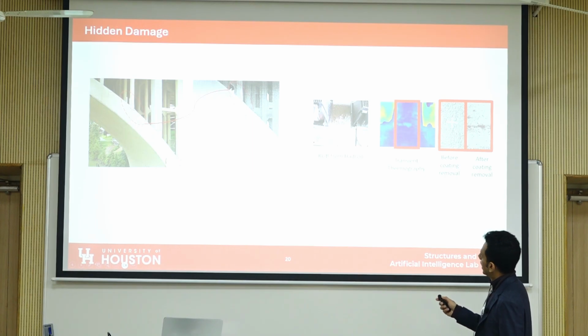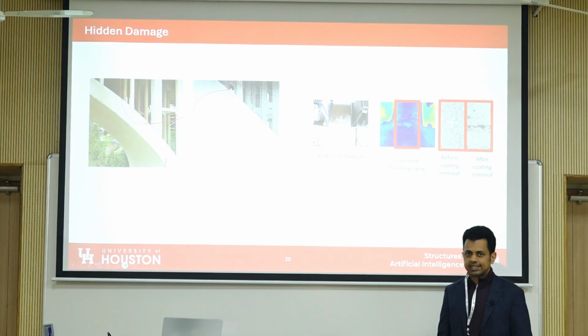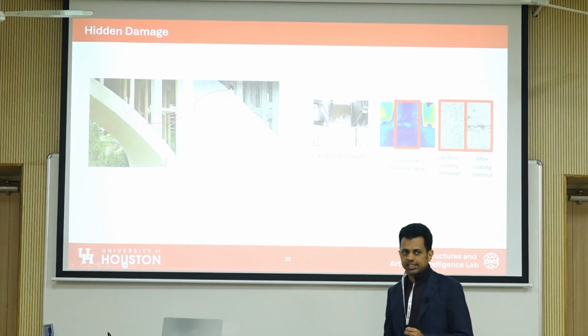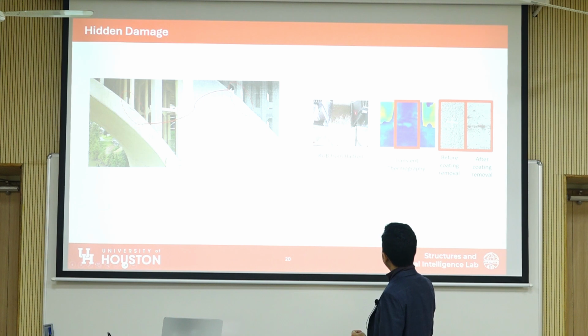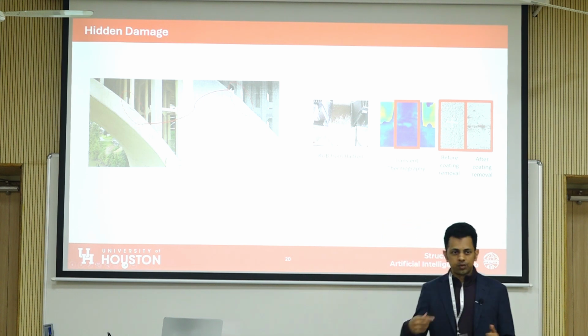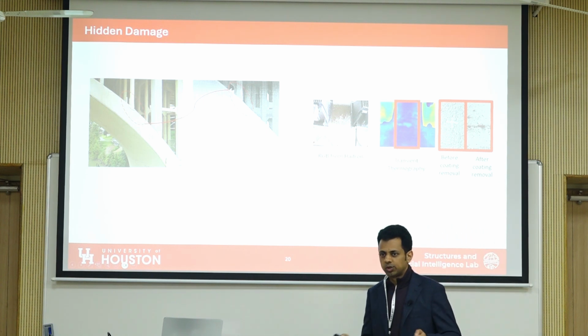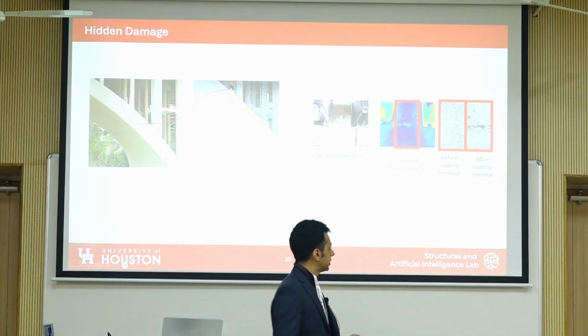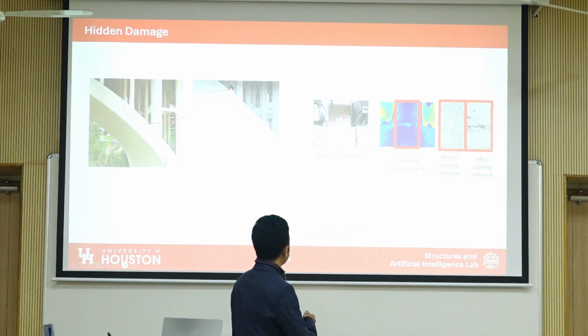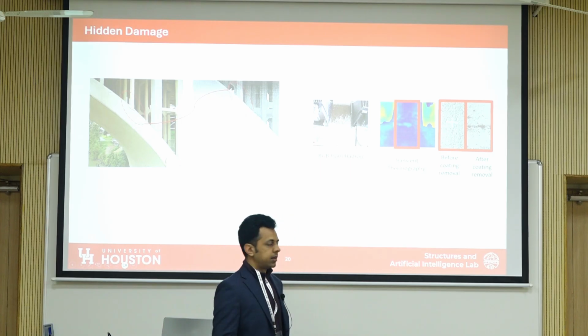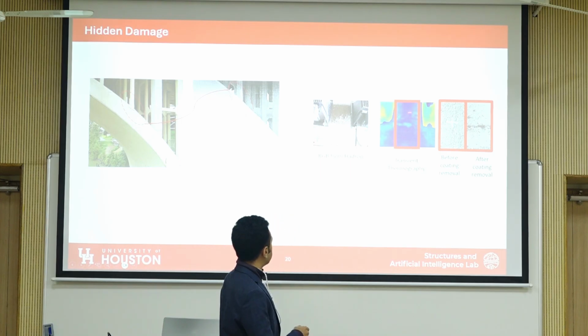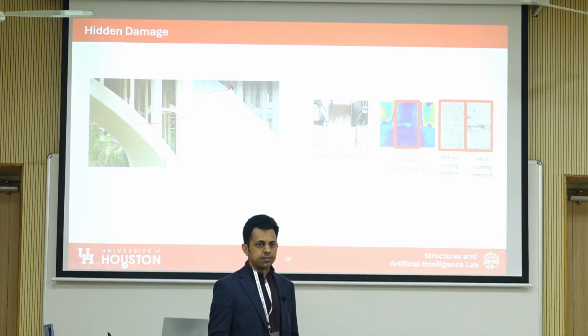Now here is a deck. It's a steel deck on a ship. And here there are two halogen lights, and so we're using the halogen lights as a heat source to heat up the surface. But here you can't really see any corrosion, right? But in the thermal response, you can clearly see that there's a patch in the middle.